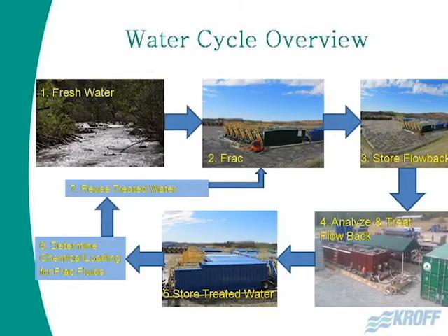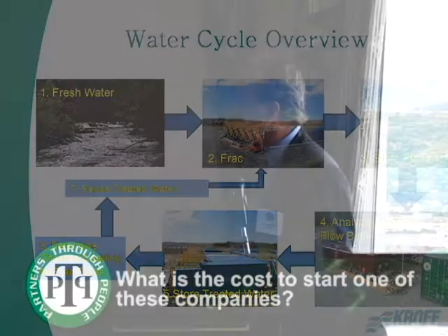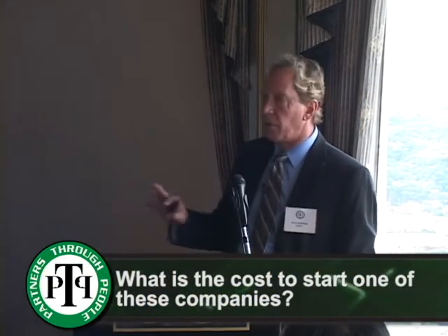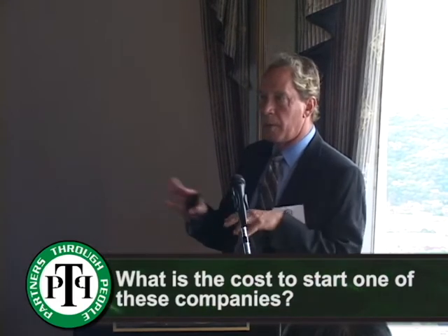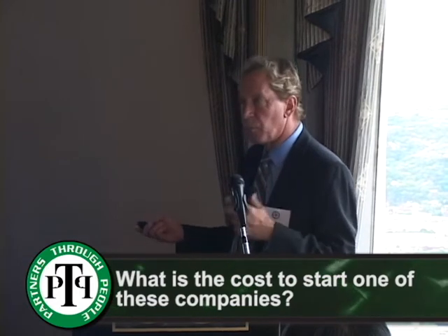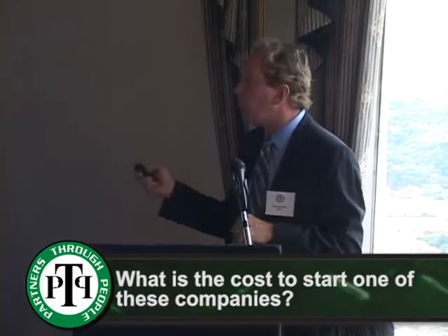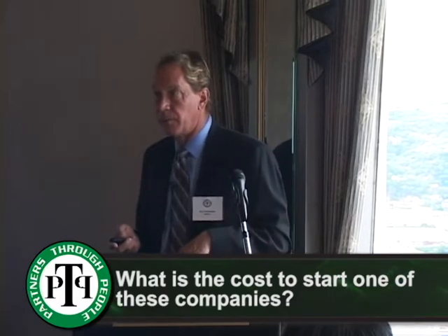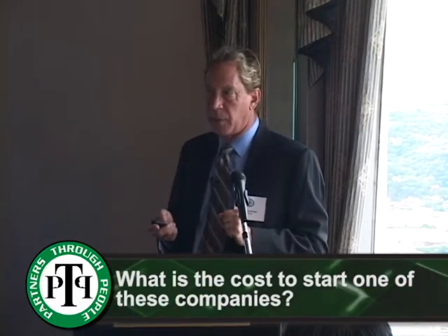Look, this guy made that. You buy that used, you rent that, and that's a party tent. I don't know that he's got 400,000 or 500,000 into that. And this guy's got about 1.5 million. The nice thing about this one, it's all new equipment, and it's all automated, level control, PLC driven, everything's cool. So that 700 to 1.5, these treat about 200 gallons a minute, or 288,000 gallons of water a day.